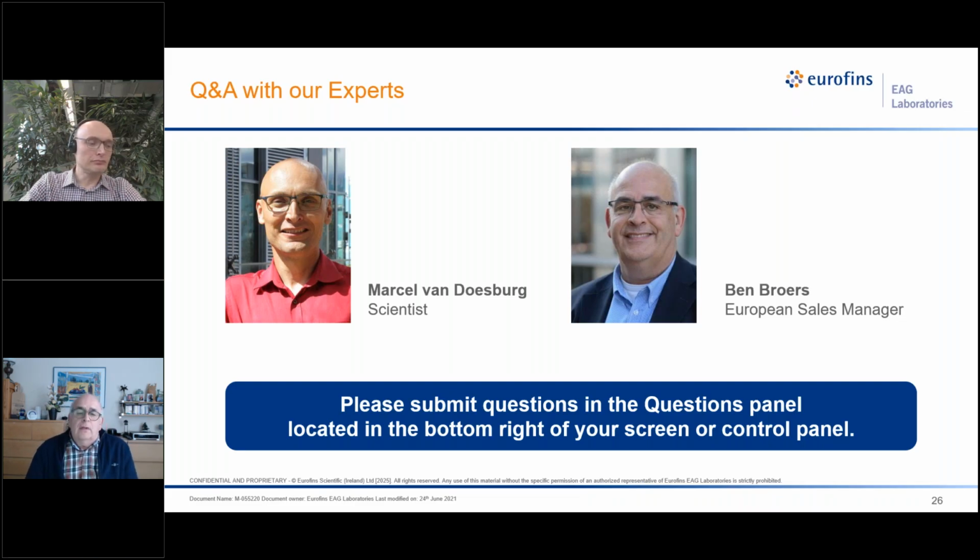Okay, thank you. Another question I have is, can accelerated aging tests be used for all types of products? It can be used for a lot of products, but sometimes, for example, organic products like food or pharmaceuticals may not react predictably to accelerated aging because their degradation is also influenced by biological factors. And sometimes highly specialized or one-of-a-kind products may not have enough comparable data to determine suitable, let's say, test conditions.